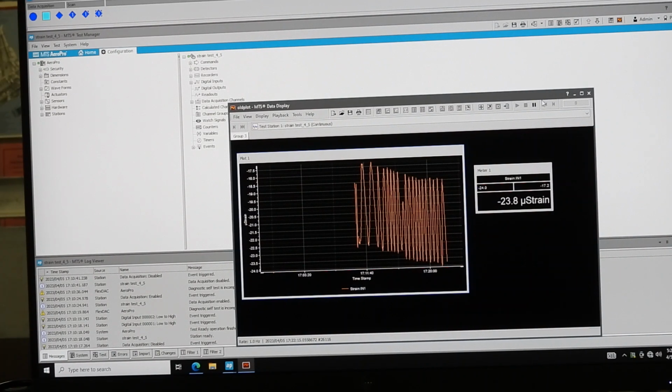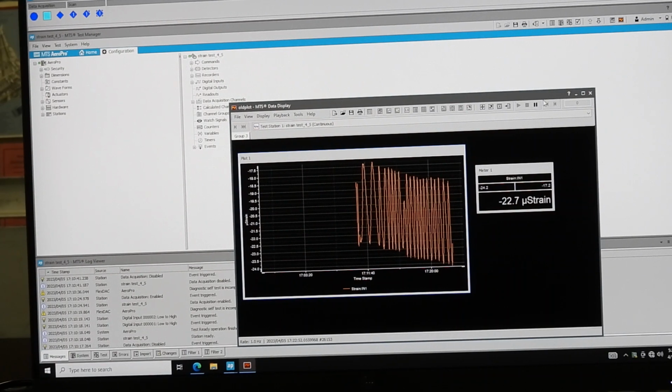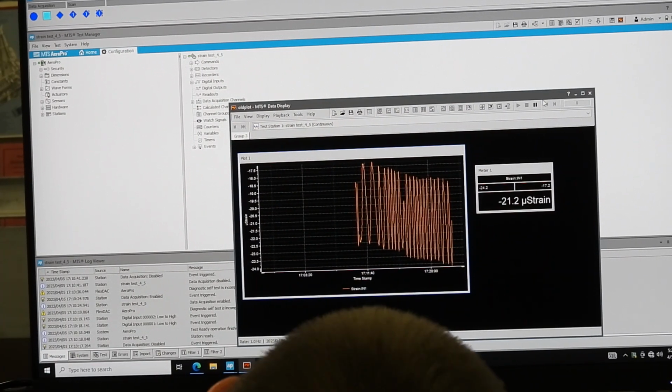But the other end is an Ethernet. There it's RJ50s. Typically here it's RJ45s. So 10 pin. If they're going into the 60, then they're the RJ45s. Well, I didn't know the difference. Those are RJ50s, those are 10 pins. These are RJ45s, these are 8 pin. They stuff two more pins. I think they're the same width. I don't know if the spacing is the same, but